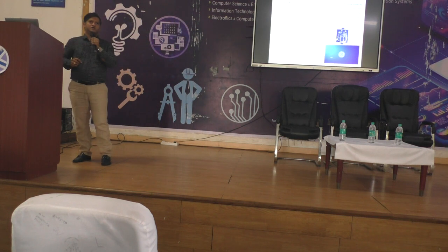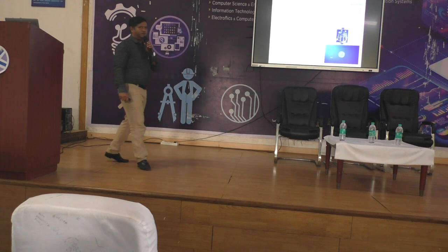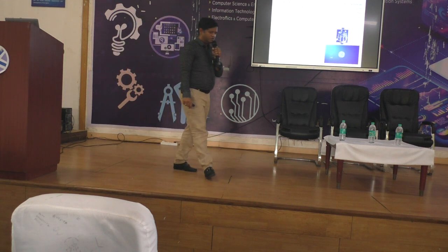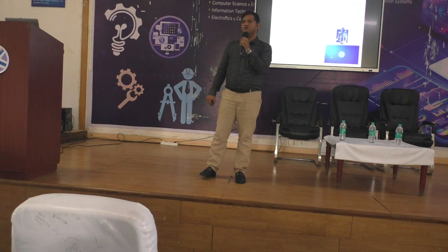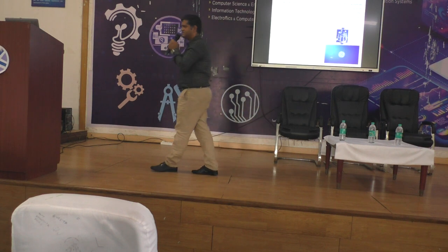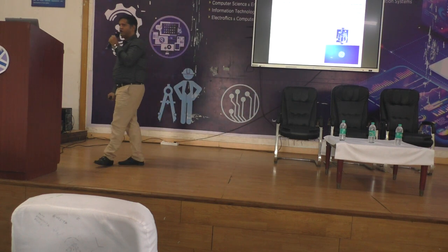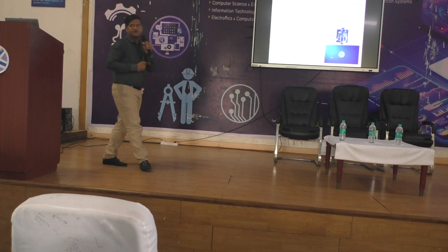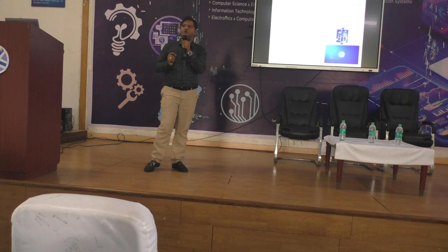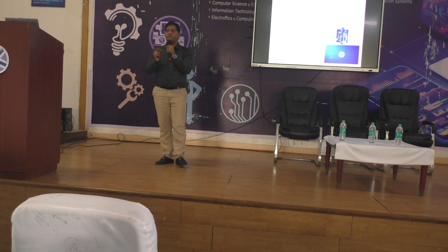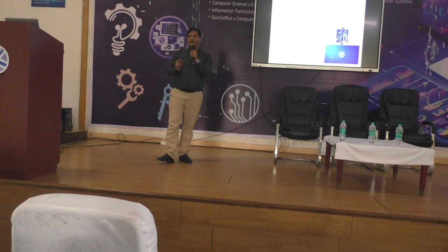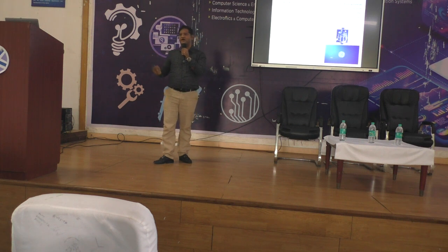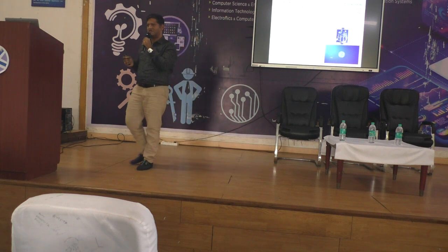Now, during this product development cycle, if you use the conventional manufacturing process to make the prototype, it tends to increase the product development cycle. In the sense, let us say if I want to make a product with injection molding, I need to make the tools, dies, and these dies will take a lot of time to manufacture. And now with each design, if you manufacture fresh dies separately and continuously, it increases the overall product development cycle.